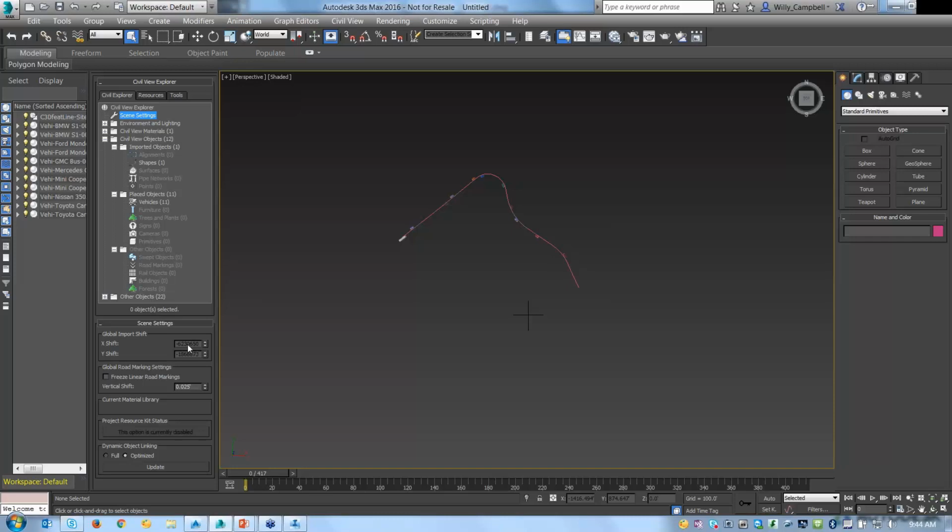Looks like 8 digits and a negative bunch of digits here as well. What that means is it moved all of my information close to 0, 0. So if I were to import this back into InfraWorks as is, it would line up roughly at the center of this data, which doesn't line up with our InfraWorks model.